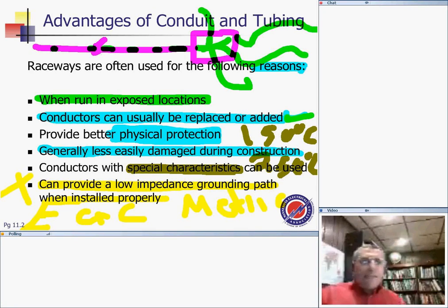But if I have my choice on my projects, I would say at least the home runs will be in conduit to the J box, a square J box, 4x4 or deep square, and from there I can allow the contractor to use MC, AC, or any other cable, or full conduit, as a matter of fact. Any questions?